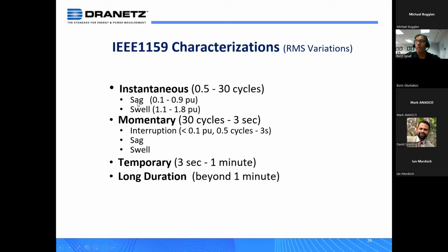All right. So that's basically what the meter is doing. It's looking for the magnitude, doing high-low limits based upon that, and measuring how long it's gone out of limits. Now, one point of note here is that on a 3-phase system, this time counter starts when the first phase goes out of the limits. And these are the plus or minus 10% or whatever you set the meter to. And it ends when the last phase returns to normal.